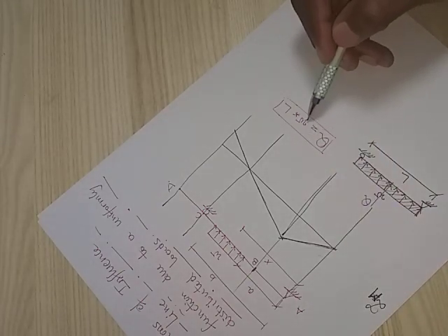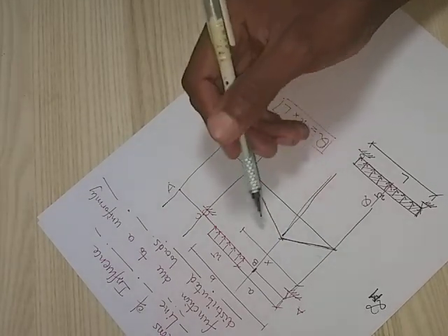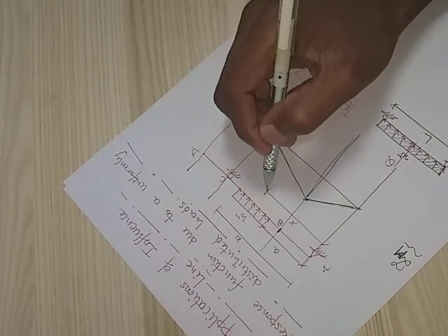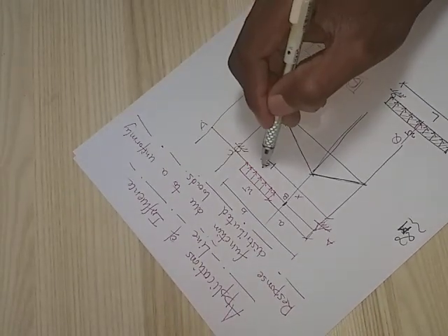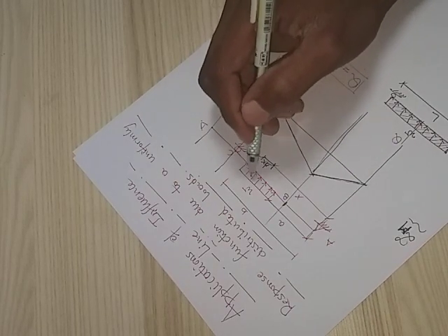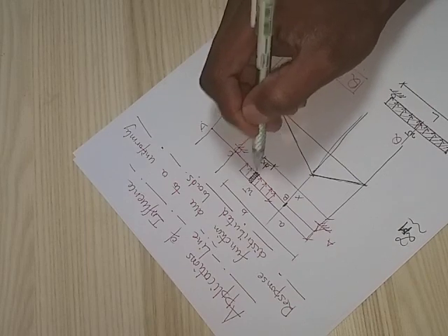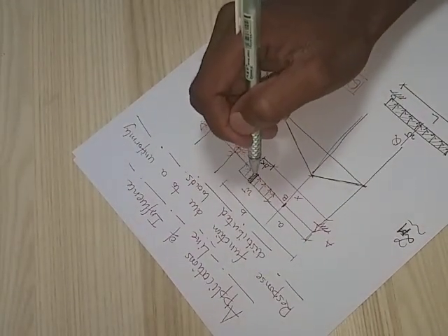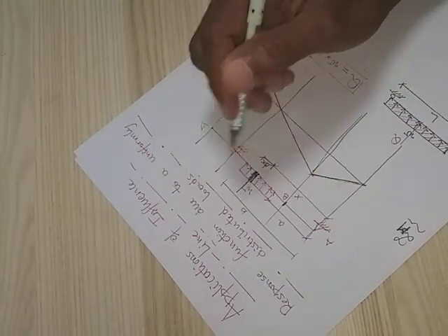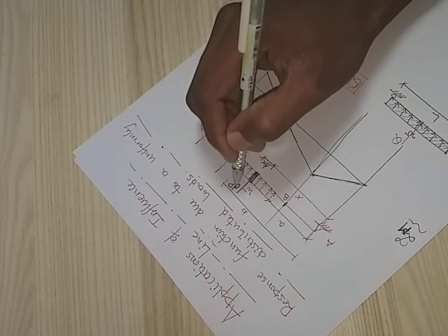We're gonna use the same principle to calculate the bending moment. Let's consider a simple element called dx. This differential element, we find it here on the distributed load, is this portion. Under this portion we will have an equivalent concentrated load, but it will be a differential concentrated load.